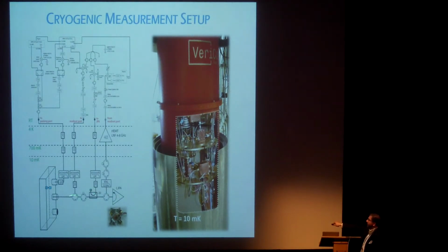The problem is I have these non-reciprocal devices shown with circles here. If I don't put them in there, I don't have a k vector, I don't have directionality, so microwaves will go back and forth. These rely on a type of Faraday rotation, if you like. So they have magnets, they have other things in ferrites. And they are lossy at the level of 1/10 of a dB or so for the best ones. So that's my only loss in the problem.